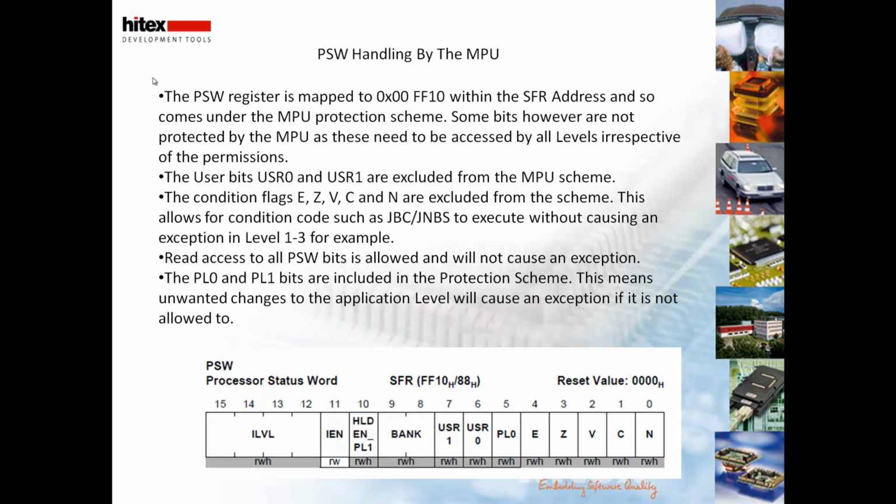Setting up and configuring the memory protection unit initially is very straightforward. You can create a large structure to contain all of the different ranges and all of the different read and write permissions, and then you can have a small piece of software which actually writes these into the various memory locations. As you have a read capability as well, you can read back all of the ranges to verify that you've set the ranges up correctly.